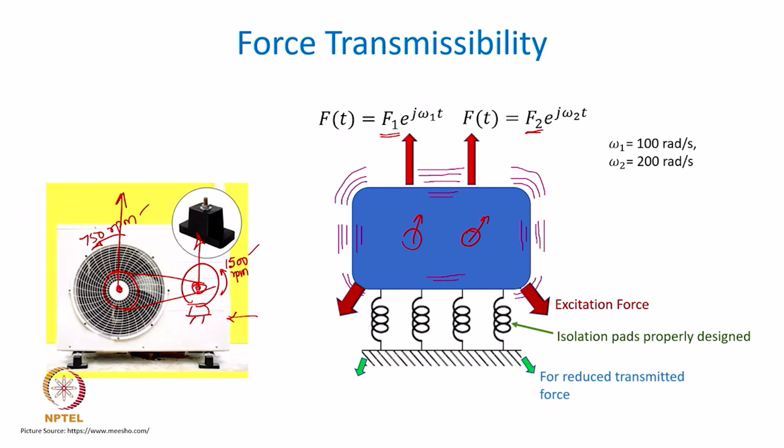Okay. How do we do that? We have just seen in the previous slide that we properly evaluate the value of K as well as C. Now, we have seen how K is important. K is important for influencing an appropriate natural frequency, but that natural frequency is related to, in the sense it depends upon what omega is. Omega n is decided or designed to have a certain value depending upon what omega is, okay, which for a given fixed mass will only influence what is the value of K.